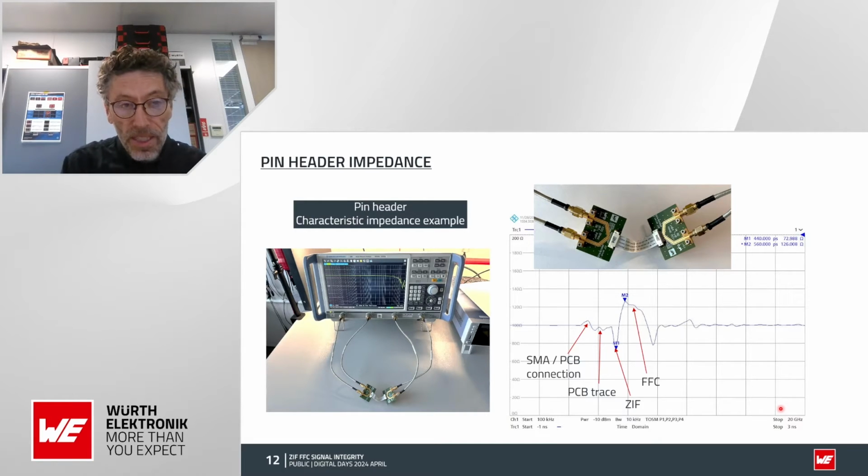So, last thing before we go into the figures: how the measurements are done. We use a Rohde & Schwarz VNA here, 4 ports, and you send different short pair signals here, and you do the measurement here. What you see here is that for the impedance, you send a signal. This is 100 ohm because this is the measurement of the coax cable, 50 plus 50, so 100 ohm. Here you've got the connection of the solderless SMA. You see that there is a small impedance change.